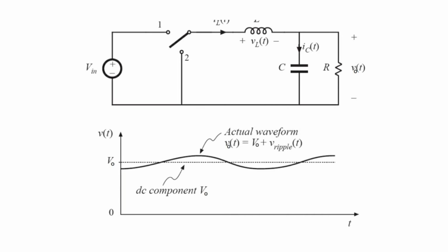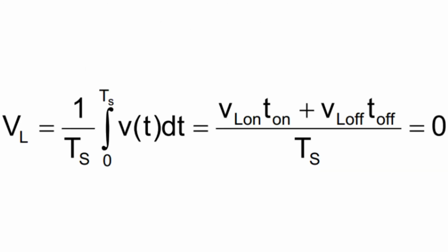Now I am going to add the inductor and diode. The inductor has the property that it will not let the current go to zero. So at on time it will charge, and at off time it will discharge. So the wave looks like this. This is enough for understanding. Now let's move towards some mathematics and the design of it.